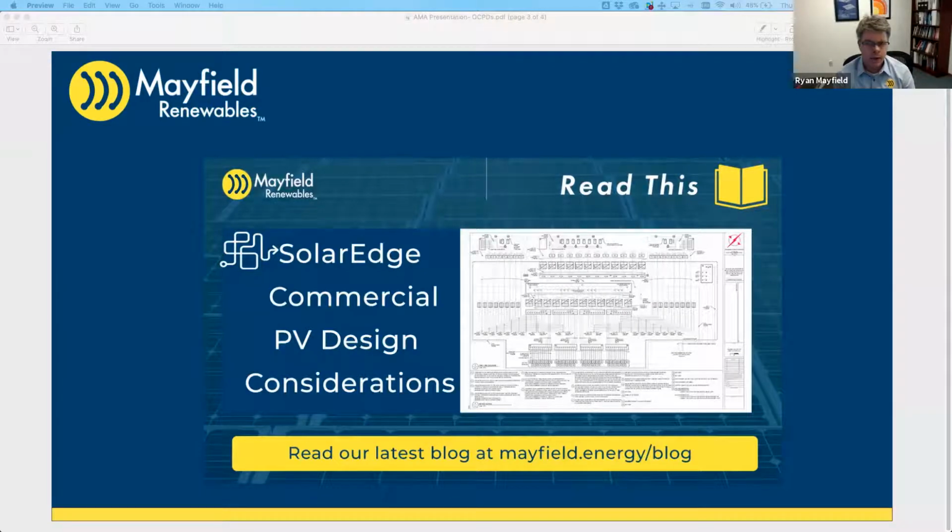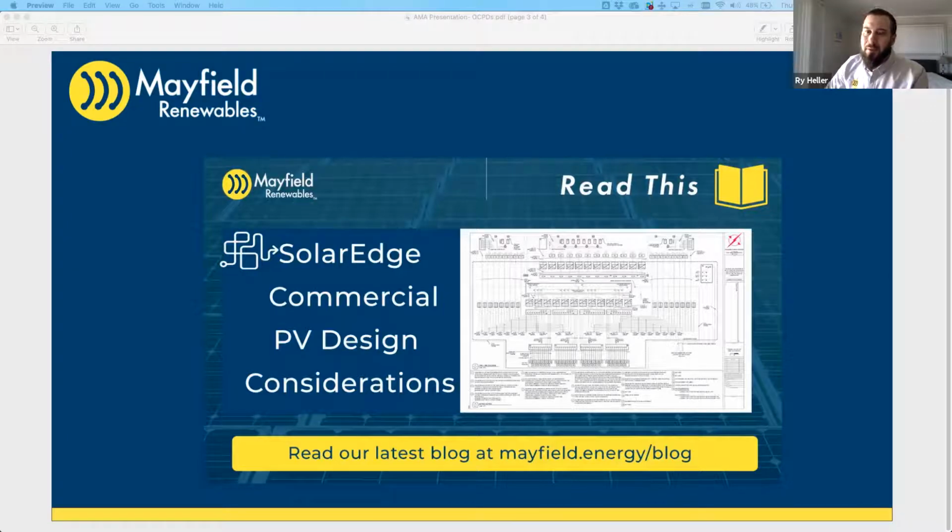So I think now with the number 6-gauge minimum requirement, it feeds right into that code, and it just makes sense, especially if you're using those type of connections that are biting through the sheathing. I've always felt like it was best practice to at least have a number 6, if not bigger, just for something to bite into. Sure.